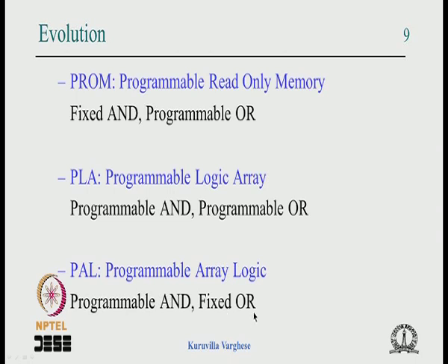Now, the idea of this PAL has come from using memory as programmable logic. Because of non-volatility the PROM was used, which was a fixed AND, programmable OR.